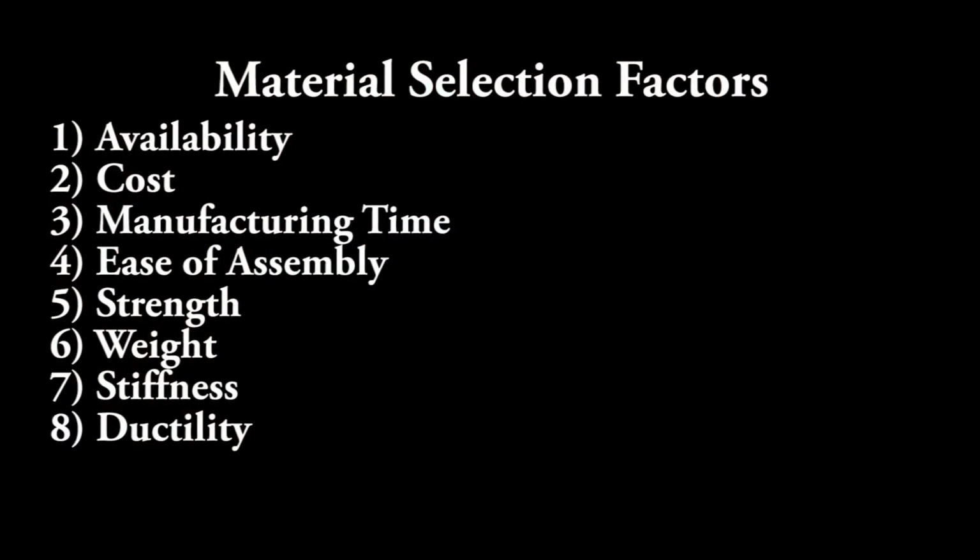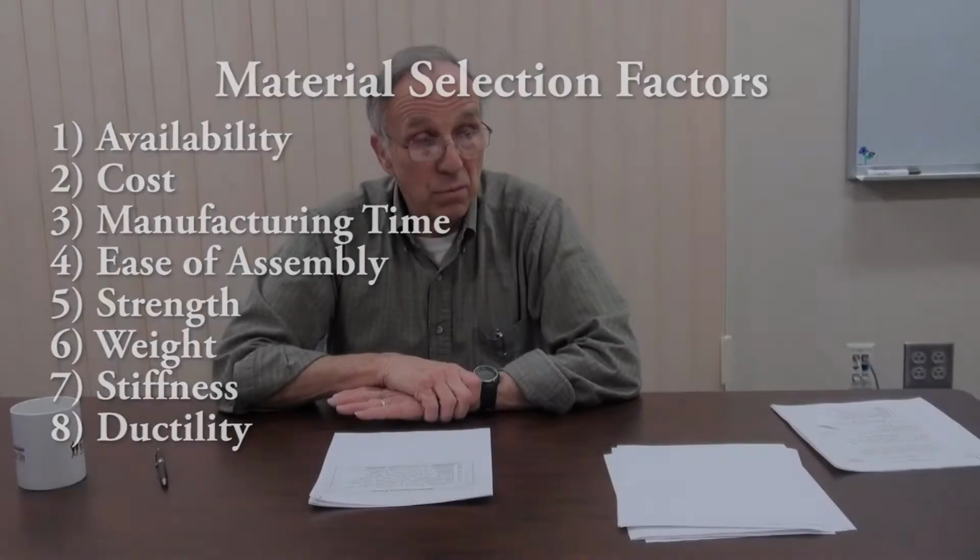Weight will impact the bulk of the material and also, well, it will impact the usability of the device. Certainly we have to think about how formable your material is, its ductility, its ease of machining or just basic operating, drilling holes, threading the holes, things like that. So essentially brittle materials are probably undesirable unless that's what your final product is, unless that's a thing you want to test in and of itself.